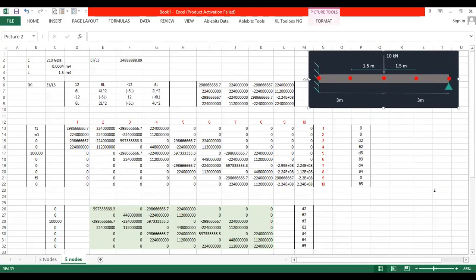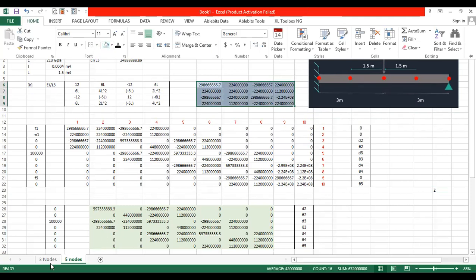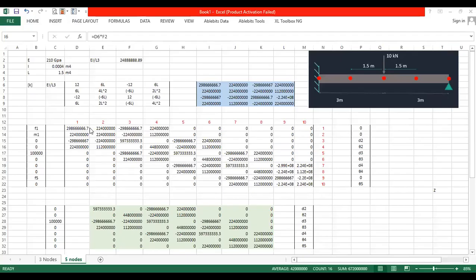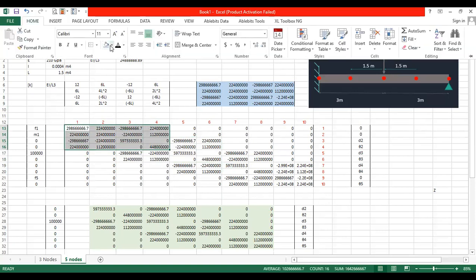Since the elements are the same, the nodes are defined at 1.5 meters, 1.5, 1.5, 1.5, so you get exactly the same element stiffness matrix for each member. You saw that in the earlier example as well, right? So I can define the same matrix. This is element matrix 1, add element 2, and add the next. You know how to assemble that.